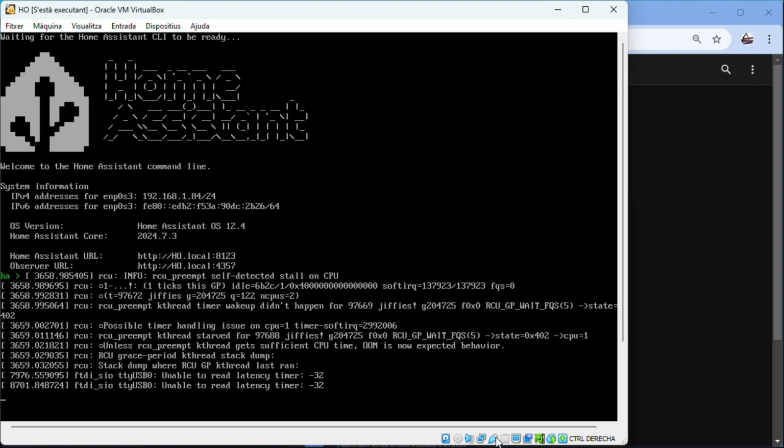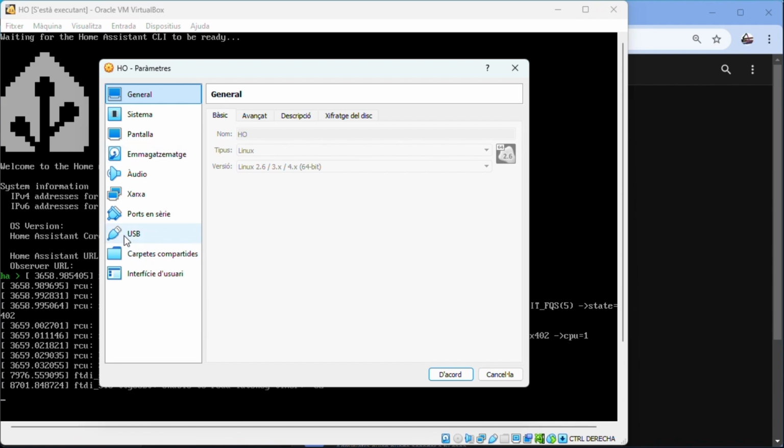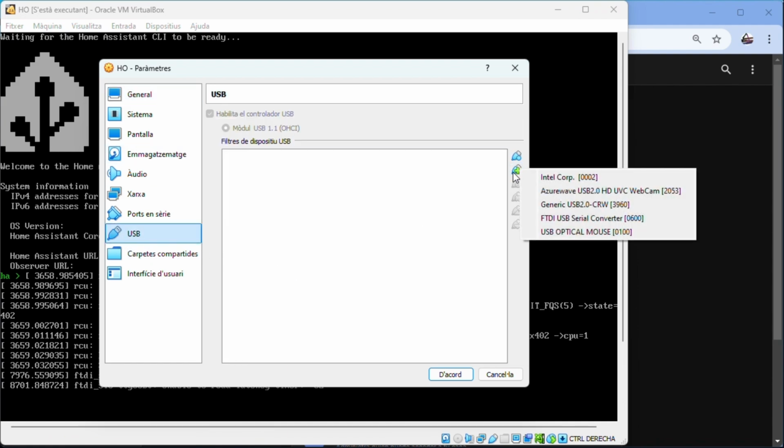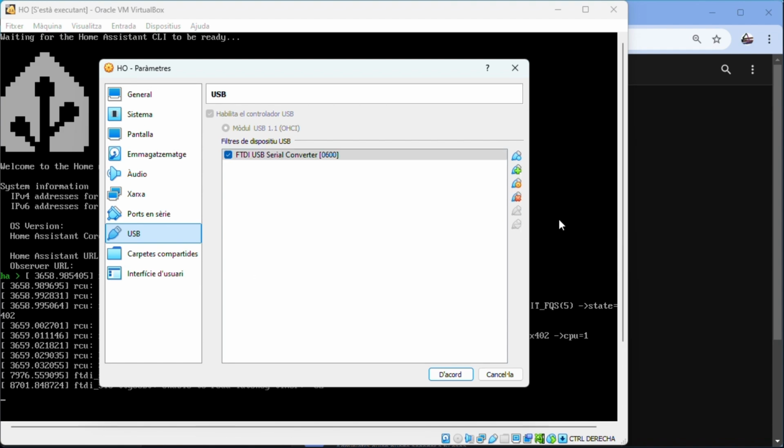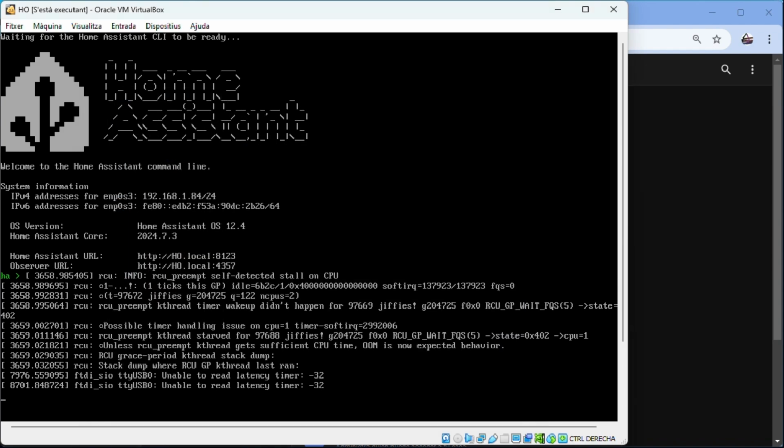If we are in a virtual machine to direct the traffic to the converter, we must enable the USB/RS485 converter. For this we must have the converter connected to a USB port. Here is shown how to do it in VirtualBox. We will add the USB device to serial.